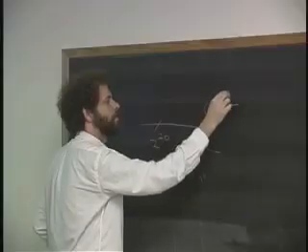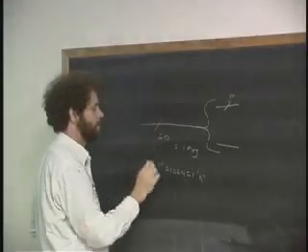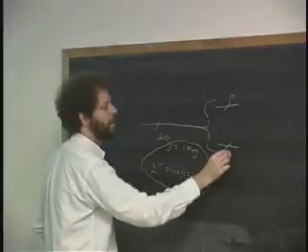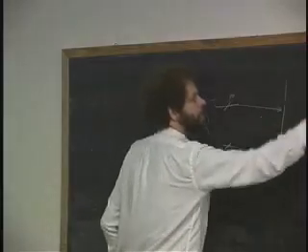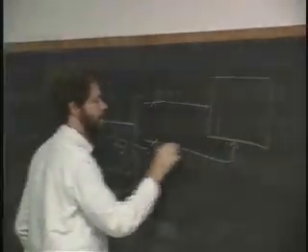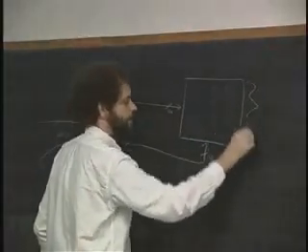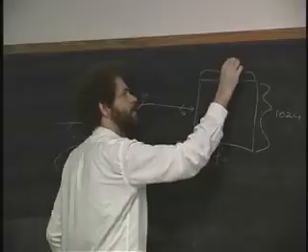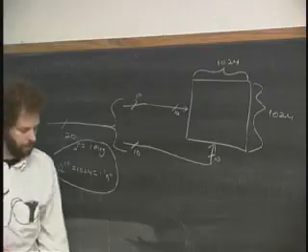being a set of bits that's going to be 10 bits wide, like this, 20 bits wide because 2 to the 20, draw this like that, and another set of bits that's 10 bits wide. And so this will then go to a structure which is square, and we'll have 10 bits here, 10 bits here, so we'll have 1,024 rows and 1,024 columns. And that's reasonable to build. Okay? So, that's how we're going to build big, slow RAMs.